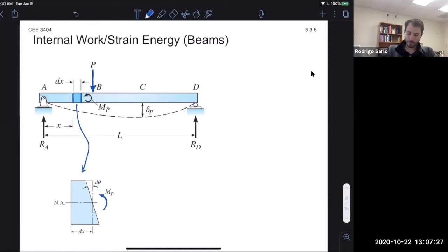All right. Remember, stresses are linear from the neutral axis. So they're 0 at the neutral axis, and wherever they're compressive, in this case at the top, they'll push the beam one way, and then when they're tensile, the other way. So the overall effect is that the beam rotates at that point. And that's what actually creates the curvature, right?